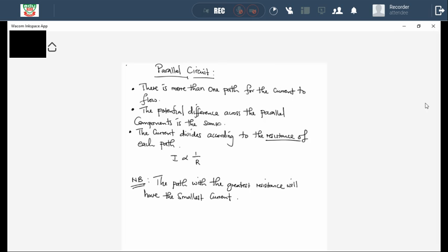And remember the last point I made last time, I said when we look at an electric circuit, the total amount of current is constant. We don't lose current along the way. So when we deal with the parallel circuit, it's not like we are losing current. It's just that the total current is going to divide and move into those different pathways, right? But immediately those pathways come together again into the main line. If we add up the total current, it should give us the original total current that we started with, right?